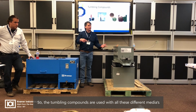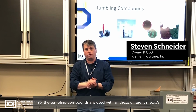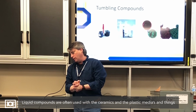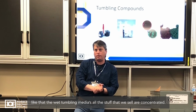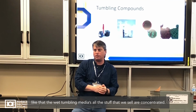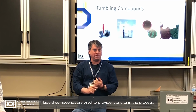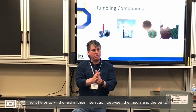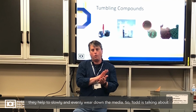So the tumbling compounds are used with all these different medias. Liquid compounds are often used with the ceramics and the plastic medias and things like that, the wet tumbling medias. All the stuff that we sell are concentrated. The liquid compounds are used to provide lubricity in the process, so it helps to aid in the interaction between the media and the parts. They help to slowly and evenly wear down the media.